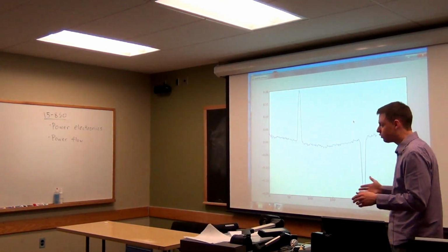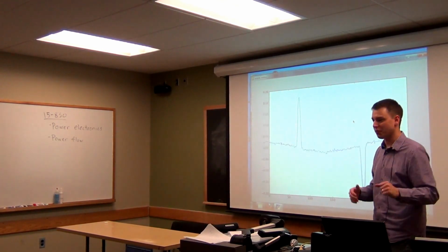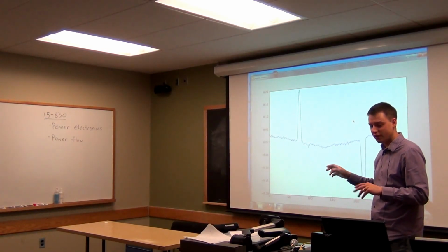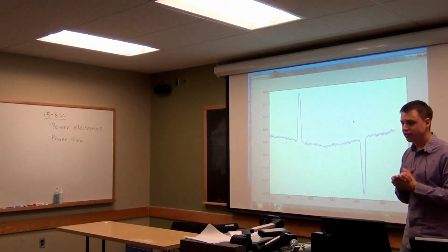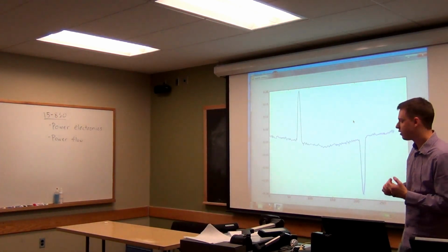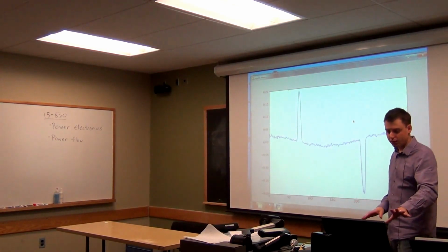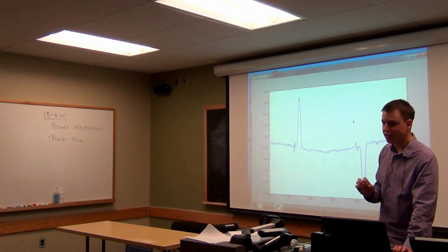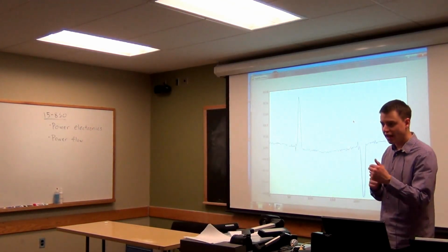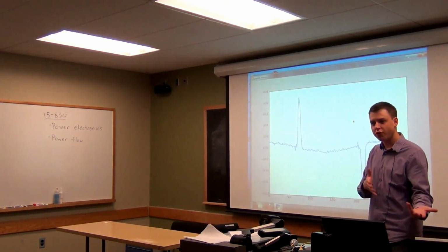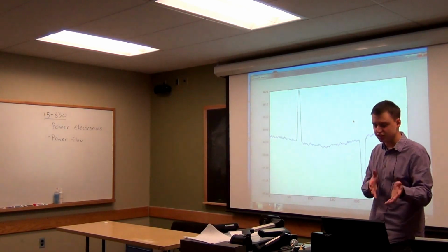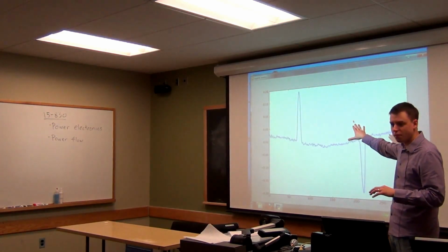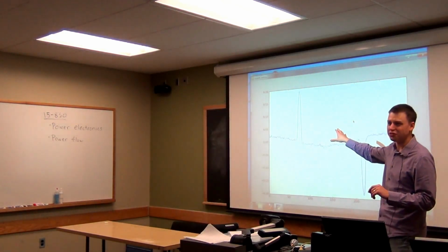And in fact, we live in a world where virtually everything, or most everything we have, does this kind of stuff to power and electricity. Because whenever we're powering electronics, we typically use systems that will somehow mangle the current. My laptop here doesn't take AC electricity as its input. It takes DC power. It's much easier to use direct current at some lower voltage. So it's doing all sorts of things to convert AC to this DC voltage source. And that kind of stuff wreaks havoc on these current signals that we actually see.